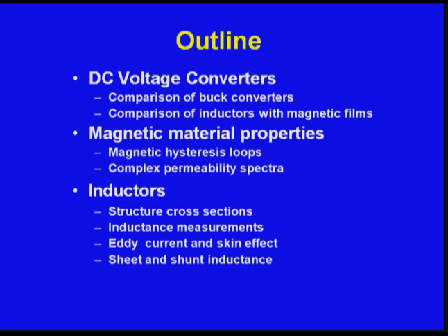And then I'm going to go into some material science, and so hopefully people will indulge and perhaps enjoy something that they may not have seen before. Particularly, I'm going to be looking at magnetic materials. And then the third part of my talk is going to be looking at inductors that are fabricated with these magnetic materials, the fully on-die inductors, and what we were able to achieve.